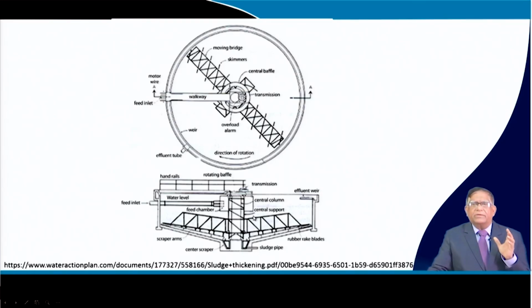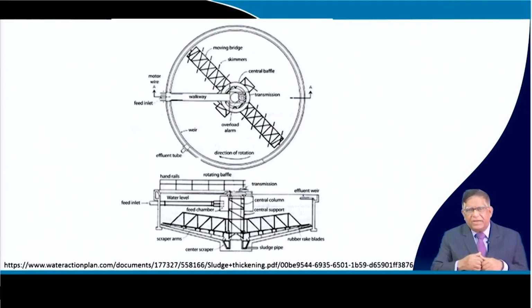So, for the whole design, you can have a lot of innovative ways of putting it. Now, whatever is available in the field, in the market, in the industry, as a case study, you can see that those are mainly decided depending on what type of sludge will be coming. Sometimes in some processing, because of the oil and other things you have added, they make such a sludge that in that hopper it may get very sticky and does not flow. At that time, we will have to provide scraping and things like that.